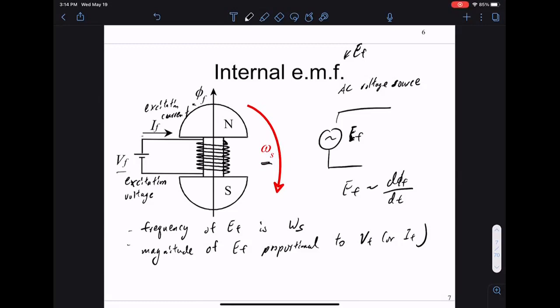Okay, so they do not produce power, right? The power is not coming from the excitation current. This basically sets a voltage level. The actual power comes from the mechanical power that's turning this turbine. So we have the exciter. Basically, you can control your own voltage. It's our voltage control. So the equivalent circuit model is